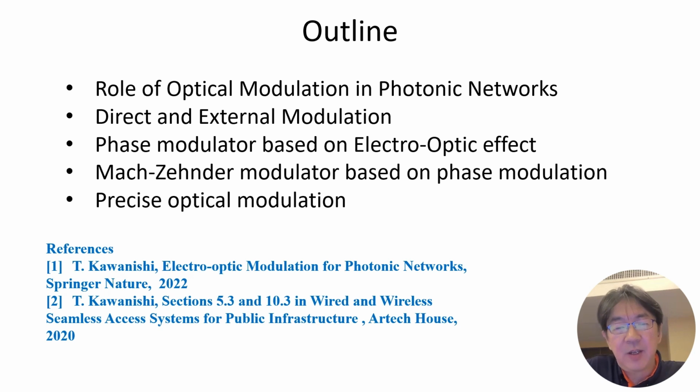Z-cut lithium niobate wafers can offer effective modulation, but we would have undesired asymmetric push-pull operation. To solve these issues, various types of advanced device structures are proposed. I showed just some examples in this presentation.